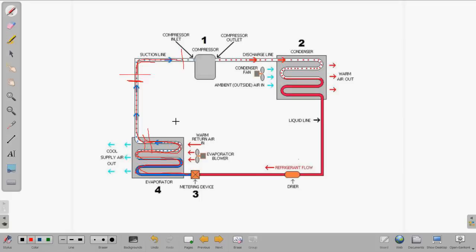As you measure with your gauges, which is again theoretically the center of the evaporator coil, the saturation temperature, and then you look at the refrigeration lines, those temperatures are going to be very close to the same temperature. I've seen them exactly the same, and it doesn't even have to be a grossly overcharged system. If it's 0 to 3 degrees of superheat, you know it's overcharged.